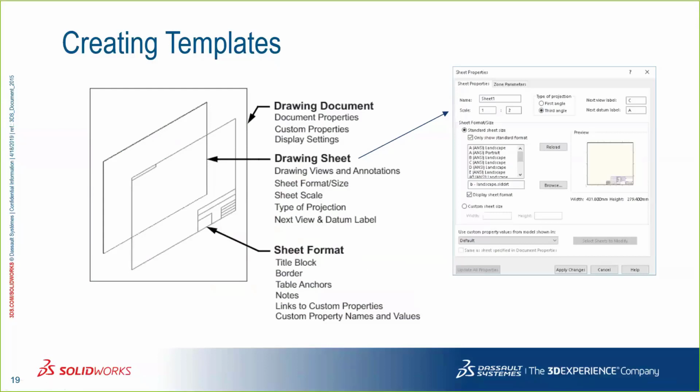So if we change our sheet format, we will have to go back and reload or reread it through our sheet properties here. And we're going to get to that during this lesson to see how that works out. A lot of times people need to do this because logos change or customers get bought out or someone has different branding that they want to use and you need to change that, but you don't want to go through all the drawings and change it manually.